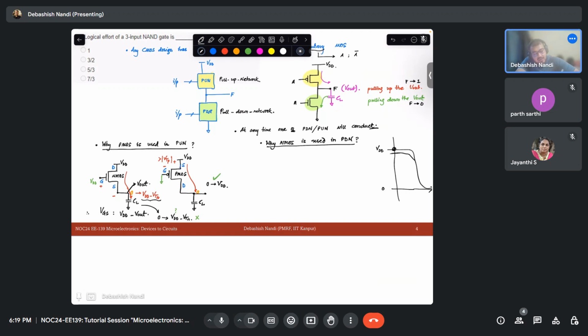So when you define, let's say this region as your 1, your noise margin starts to reduce. Okay. If you have gone through the lectures, you know about the noise margins. So your noise margin starts to reduce. So that is not a good thing. Due to the presence of noise, you cannot distinguish your level of signal as 1 or 0 clearly.